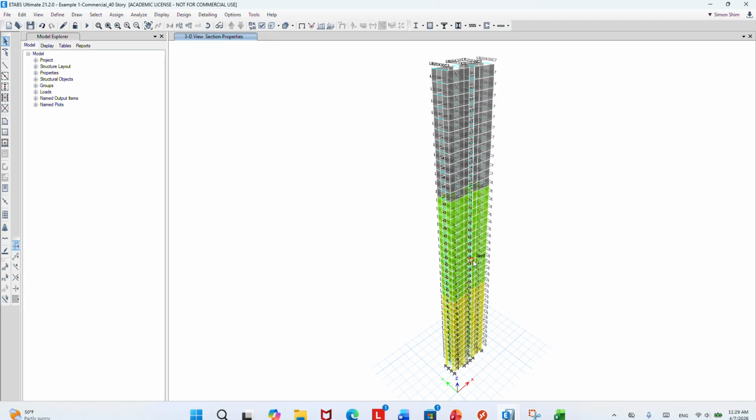The first model you ran used the default wall thickness, or if you use 18 inches, one single concrete strength, right? That's your first reference model. You have some pretty big deflection. Since you know that we need to stiffen up to meet your deflection criteria, we need to size up the wall and link beam as well. So you run the model.